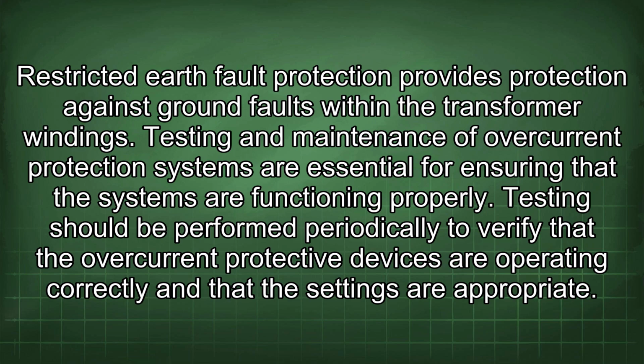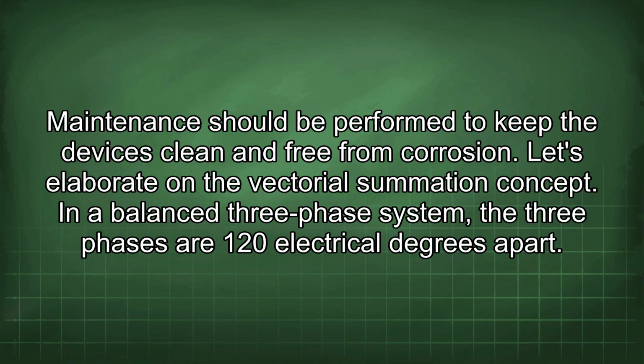Testing should be performed periodically to verify that the overcurrent protective devices are operating correctly and that the settings are appropriate. Maintenance should be performed to keep the devices clean and free from corrosion.